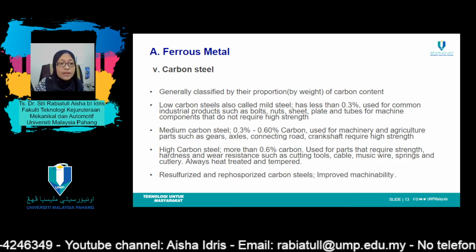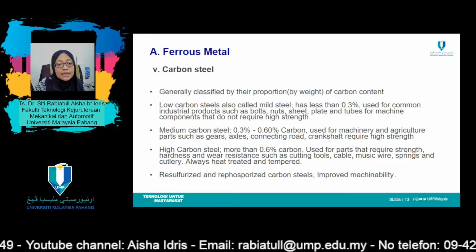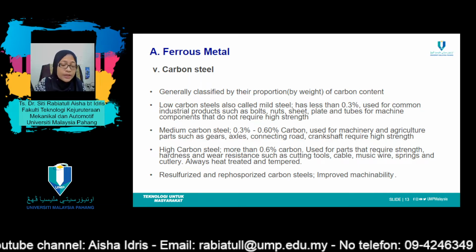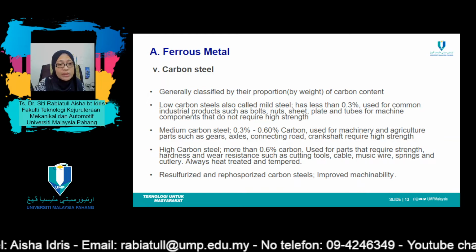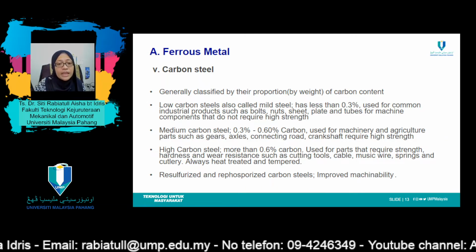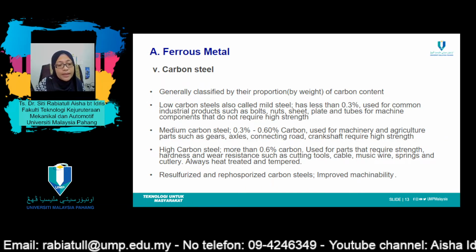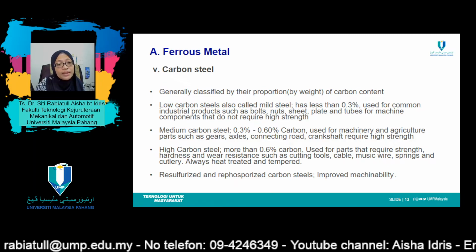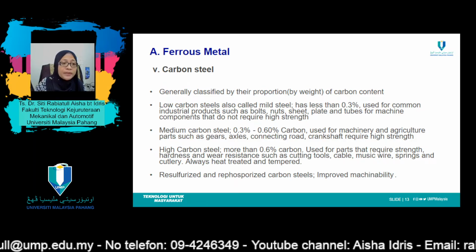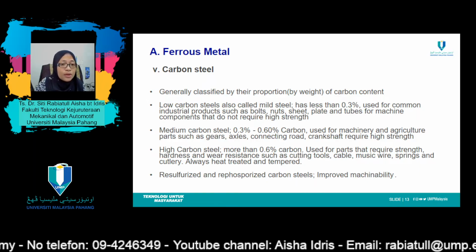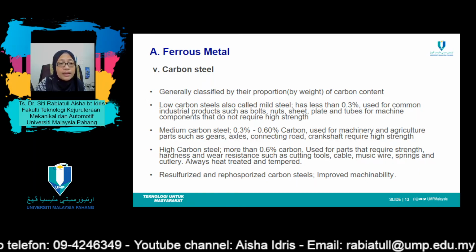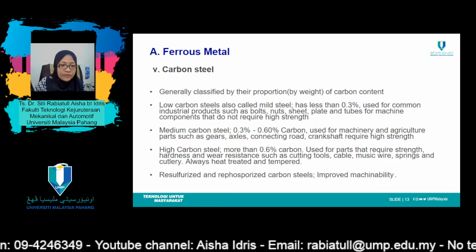The plain carbon steels have low hardenabilities and can be successfully heat treated only in very thin sections and with very rapid quenching rates. Additions of chromium, nickel, and molybdenum can improve the capacity of this alloy to be heat treated, giving rise to a variety of strength-ductility combinations. These heat-treated alloys are stronger than the low carbon steel but at a sacrifice of ductility and toughness.